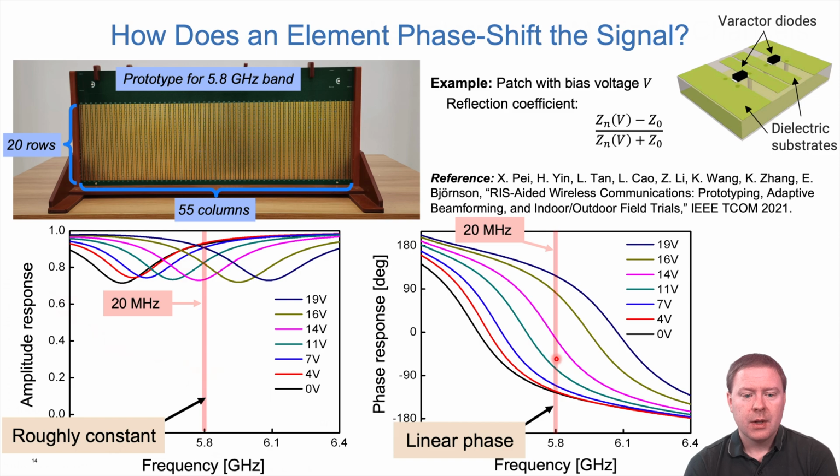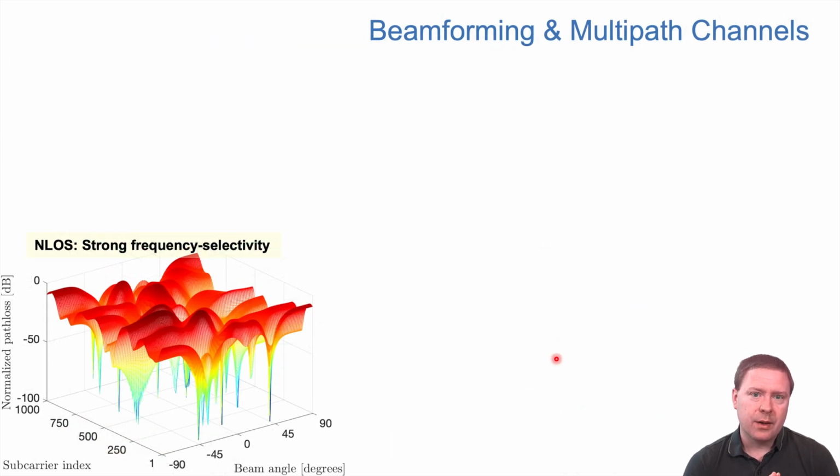So we know now that a reconfigurable intelligent surface has elements that are small and that we can control the phase shifts. And this resembles once again how beamforming can be done in 5G. There are 2 ways of implementing that. One of them is designed for non-line of sight scenarios where we have a complicated propagation environment with many different paths.